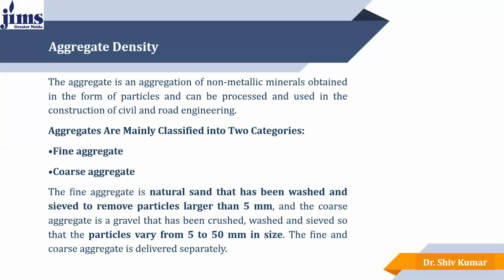Aggregates are classified into two basic categories: fine aggregate and coarse aggregate. Natural sand that has been washed and sieved to remove particles larger than 5 mm is considered fine aggregate.